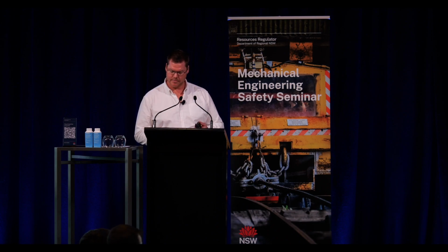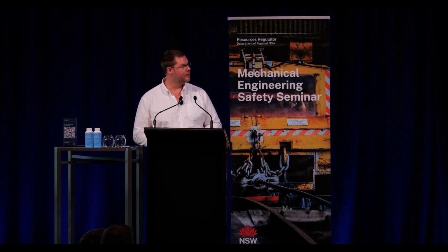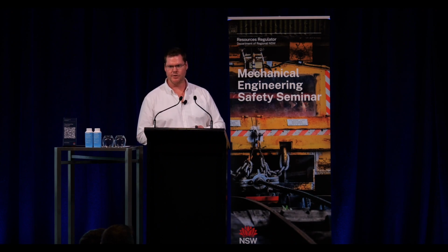So head frames, structures, they're critical in determining the tensions and loads to be induced. So it's essential during rope handling when you're potentially changing the normal operating conditions of the plant and equipment, because we are now introducing new loads that type of equipment doesn't normally see, in potentially new directions.